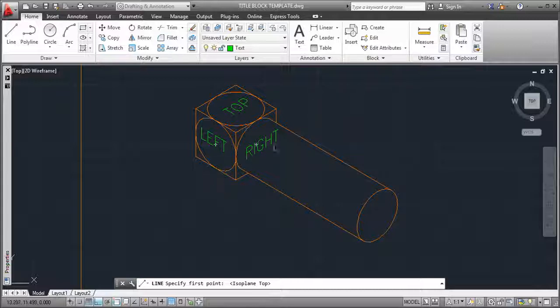I can go ahead and left click on a point, drag in this direction, and just like I create a line typing information on the command line, I'm going to drag in this direction and type 0.50. If I hit enter, it makes a line that is that length. I am going to now hit enter to finish the command.